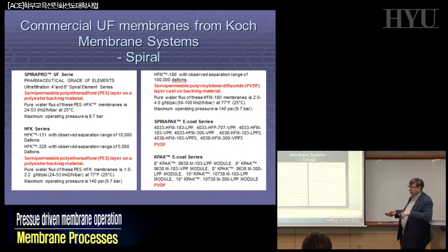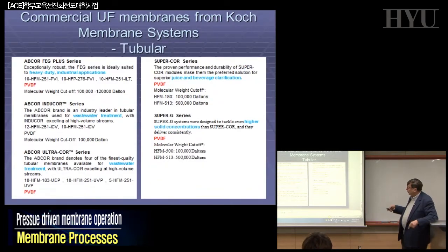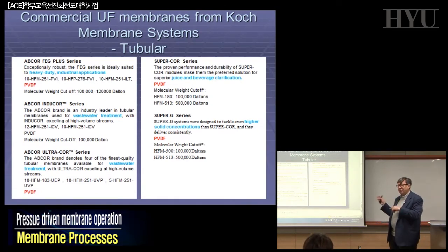So just to show you, you will find in your notes a lot of membranes with all the different concentrations, all the different separation factors, 500 Dalton, 1,000 Dalton, what they call cutoff. By the way, there's one term I did not mention before. You will find in ultrafiltration the molecular weight cutoff. This is the number. There is no rejection here, there is no permeability, etc. It's cutoff. Cutoff because we don't know how to introduce a more real way to measure the selectivity.